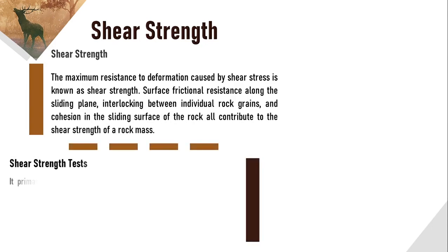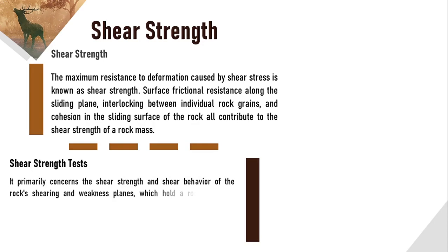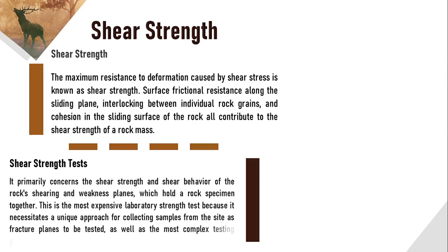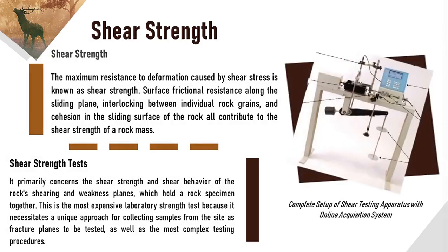Shear strength tests. It primarily concerns the shear strength and shear behavior of the rock's shearing and weakness planes, which hold a rock specimen together. This is the most expensive laboratory strength test because it necessitates a unique approach for collecting samples from the site as fracture planes to be tested, as well as the most complex testing procedures. This is a complete setup of shear testing apparatus with online acquisition systems.